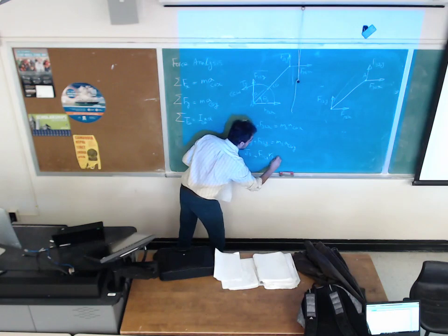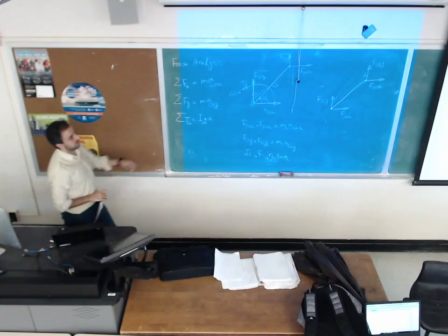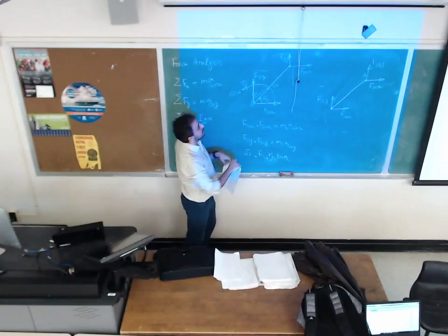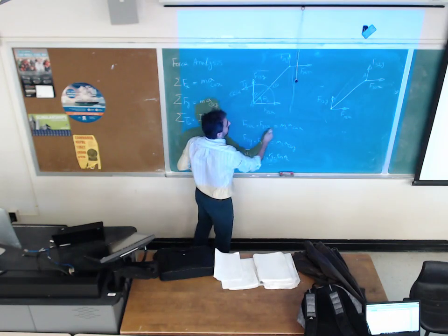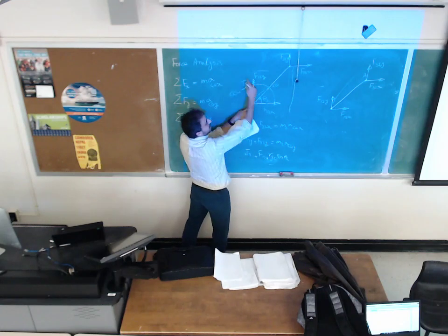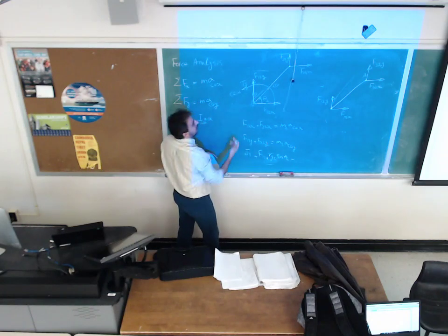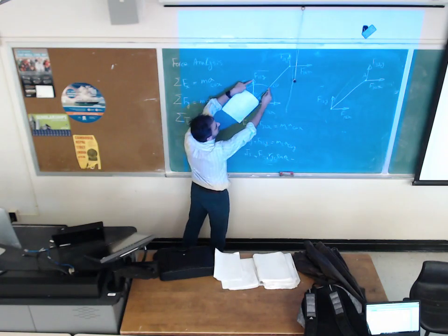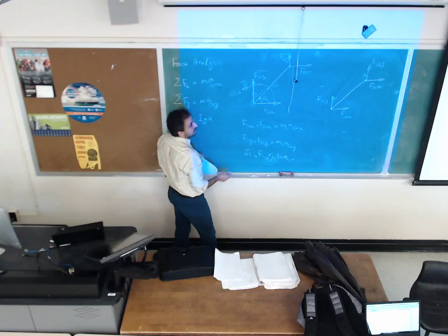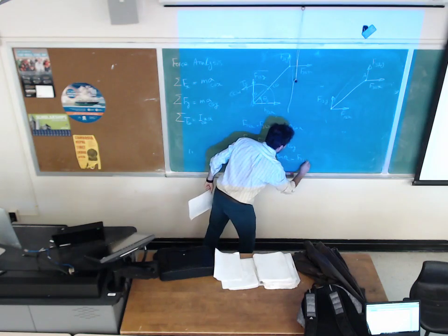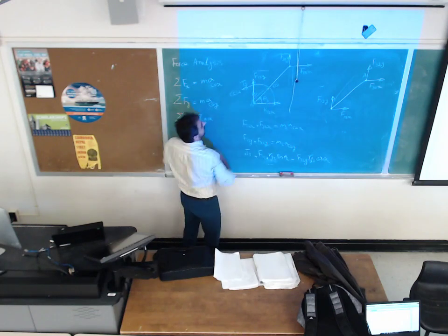Now this force times this distance is making clockwise. It's going to rotate the center of gravity in this direction. So I put negative here. How much will be the magnitude? It's going to be force times perpendicular distance. So exactly F12y times RG2 cosine of theta 2. This distance from this point to this is going to be RG2 cosine of theta 2, which is this guy.